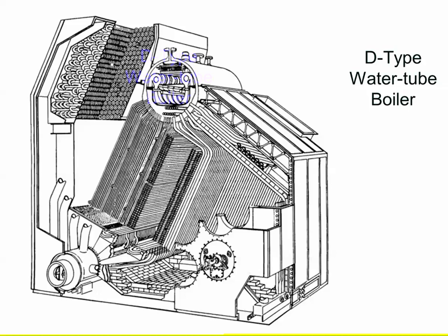When the cargo pumps went on, this demand on the boiler was fairly close to what the steam demand was when that ship was at sea under full load. So that 8,000 horsepower, when it's up and running at maximum capacity, was very close to the same steam demand of that 24,000 horsepower main engine. So we're talking big boilers.